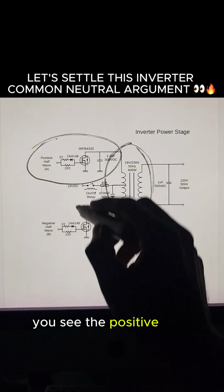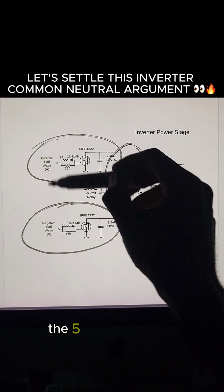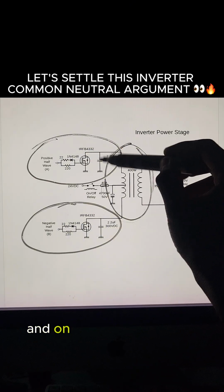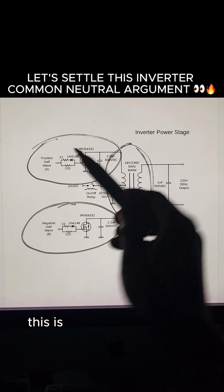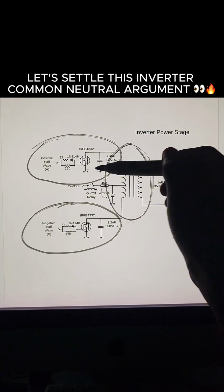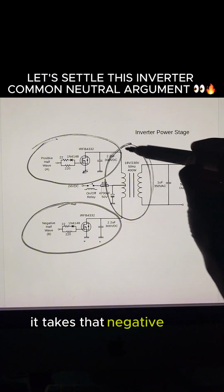You see the positive side and the negative side. This is where the oscillator feeds in the 5 volts generated, the positive side and the negative side. And on this end, the battery positive terminal will be connected to this center part of the transformer. This is the input side of the transformer now in this case. And the negative side is already connected to these two ends and these two ends. So whenever this switches, it takes that negative and puts it here.